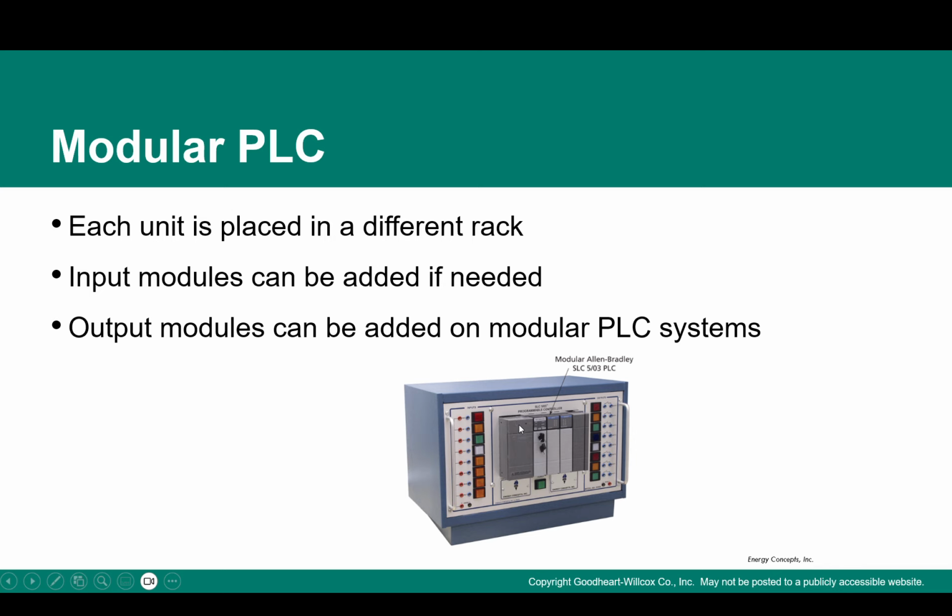For example, in the beginning, you only need one PLC like this one, and there was no other PLC. But as the needs arise, you are adding more PLCs in the modular system. Since they have a backplane, we call it the backplane bus, which connects all the PLCs together in a centralized fashion, and with the software, you can see those added PLCs and use those additional resources for your processing and programming tasks. Okay, so that's the difference between a fixed and a modular PLC.